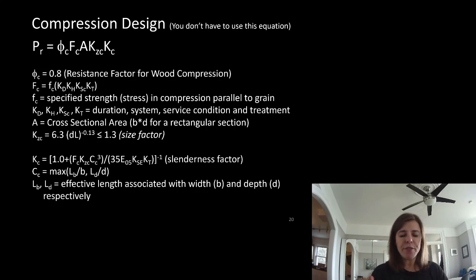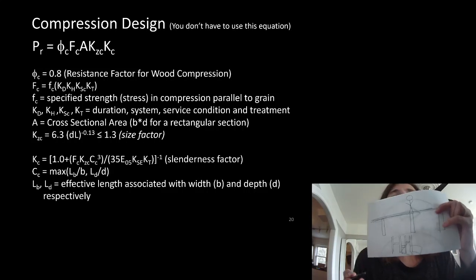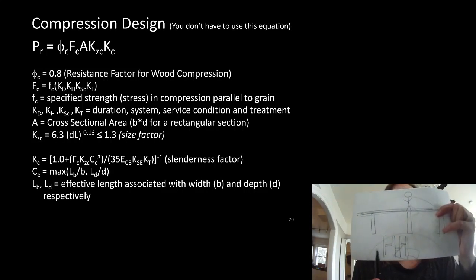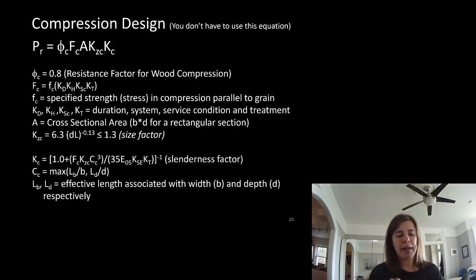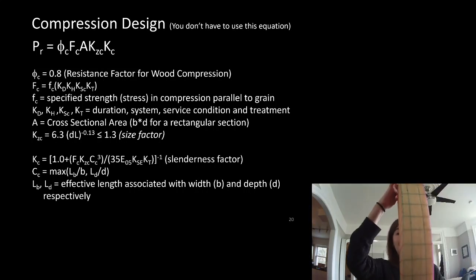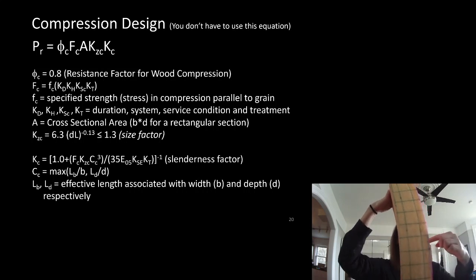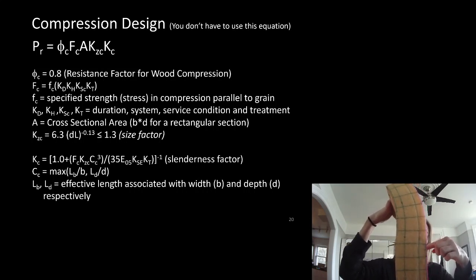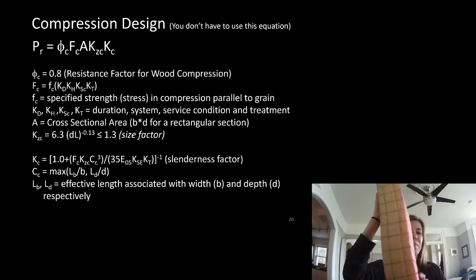Wood, often, if we looked at studs in a wall, remember, if this is an elevation of a wall and we've got studs here, we've often got blocking in between. So that is literally doing this. It's stopping it from buckling. You can see my buckling shape is actually changing here.